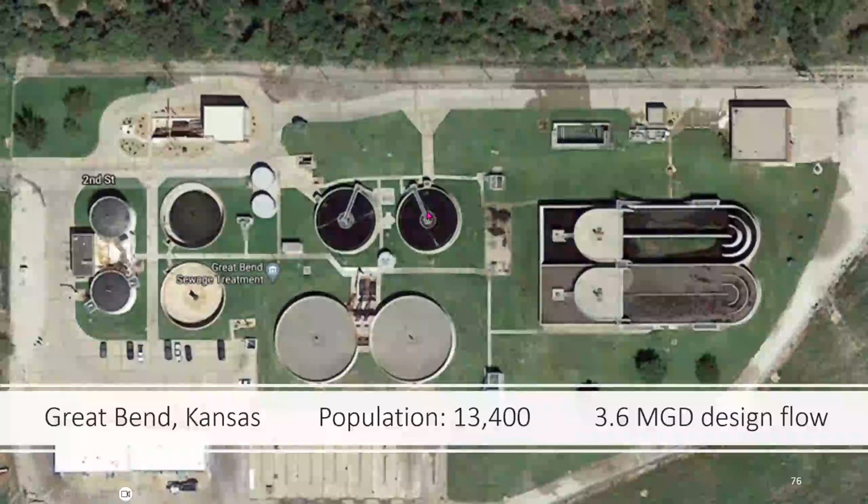And so in the case of Chancey's treatment plant, it maintains a high DO for 75 minutes and a low DO for 70. And of course, during the high DO, as this thing goes around, there's a target. Again, I'm using a clarifier as an example. It maintains a target DO by the blowers coming on and off. During the air on cycle, there's a minimum and maximum DO. It tries to maintain the target. And then during the air off cycle, it's just off. So ammonia removal during the air on cycle, and nitrate removal during the air off.